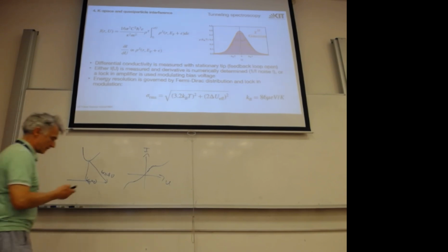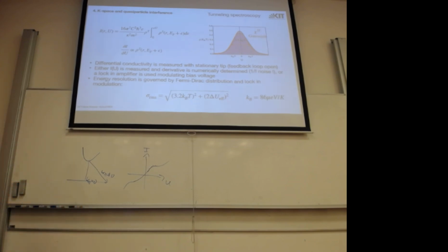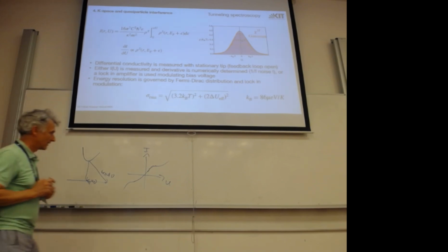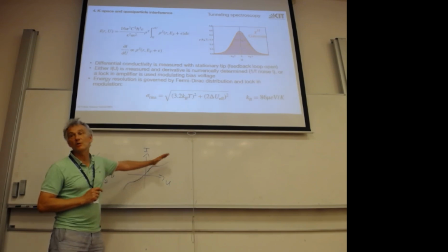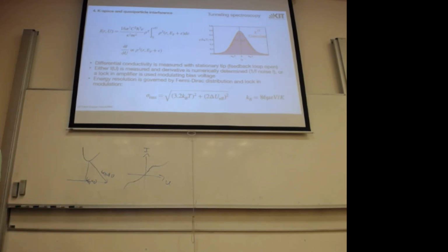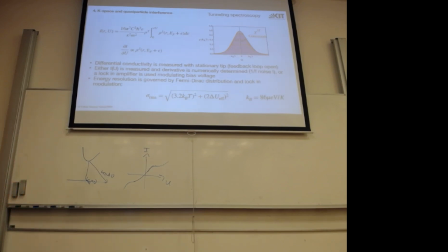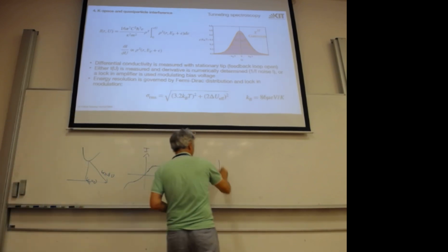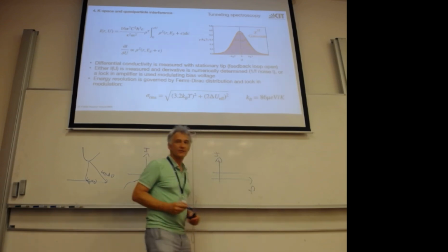Yeah, we measure the slope here precisely by repeating the measurement over and over again. But that means we look at the zero frequency Fourier component. So you measure the slope very precisely, for example, going very slowly over this, averaging very well. But it means we do the Fourier component 0. And that is a very bad idea. Why? So if we have current and we have frequency, we have the shot noise, which is constant.